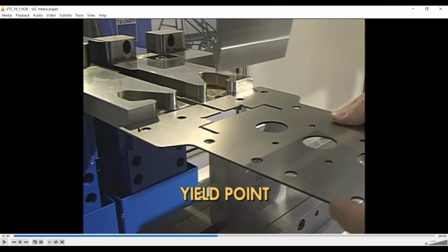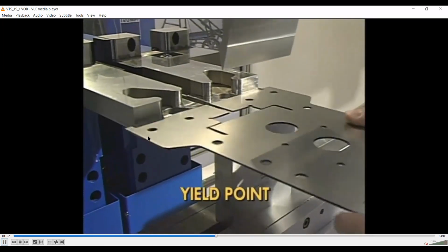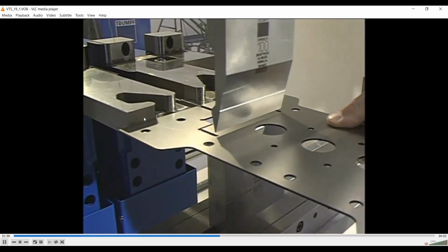That line is the layout line, and you could see the gauge that is actually helping us to position the blank in the required position so that the bend is made at the required point. So the force applied should be greater than the yield point of the metal being deformed. So this gauge is acting as a reference gauge.